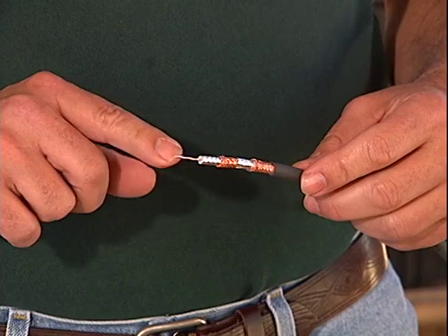Besides loss, the other most important characteristic of coax cable is its resistance to signal ingress and egress. Of the two, the most important is signal ingress, outside signals getting into the cable. Exactly. Ingress can be a real problem when there's a lot of high-powered FM stations, local TV channels, and amateur radio bands, which can cause problems with cable or modulated channels. Right. Now, defending against signal ingress is the job of the coax shields.